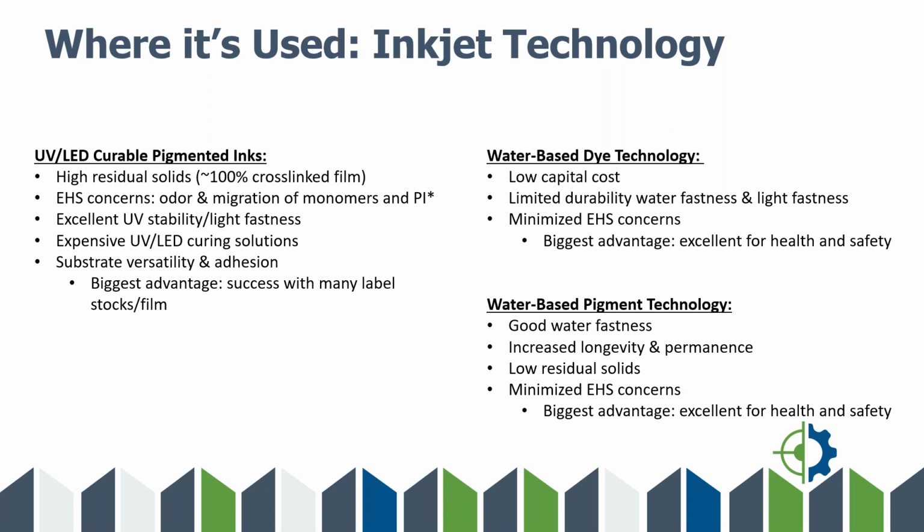With the water-based technology, like I said, less EHS concerns, and typically on some of that technology you are seeing higher resolution, but that's starting to become more equally managed as mechanical piezo print heads and UV inks are putting smaller nozzles and smaller drops down to the page.